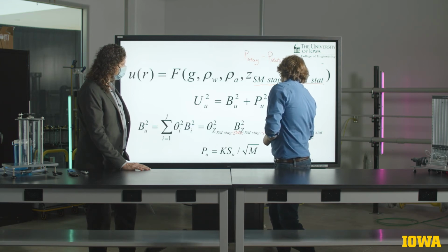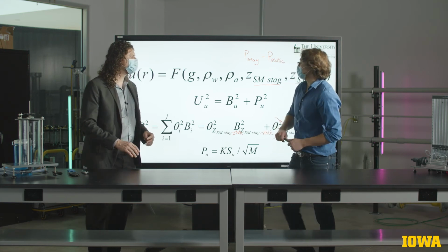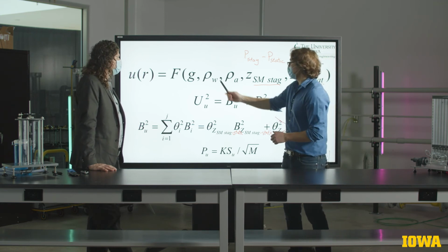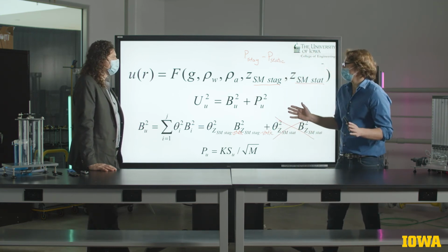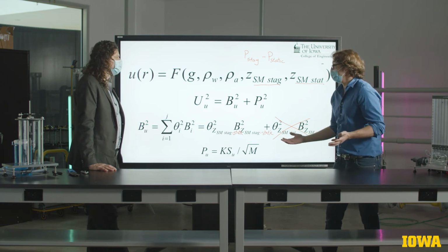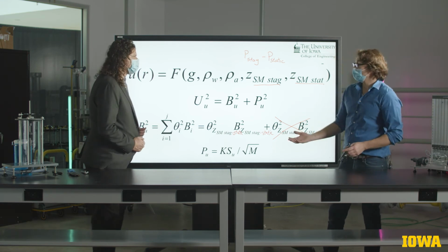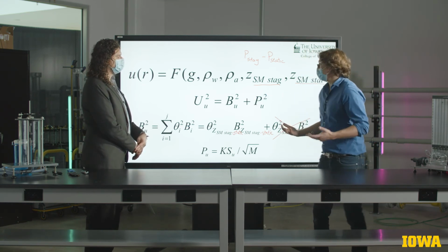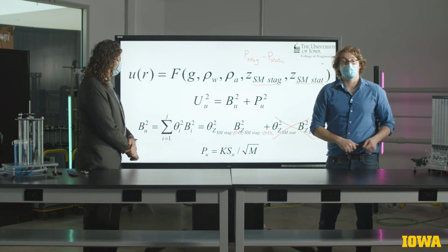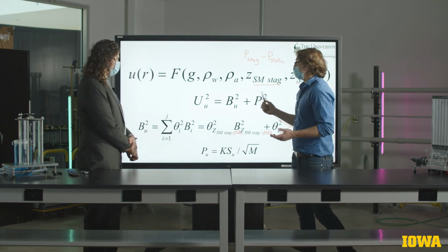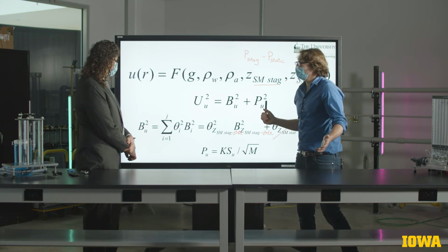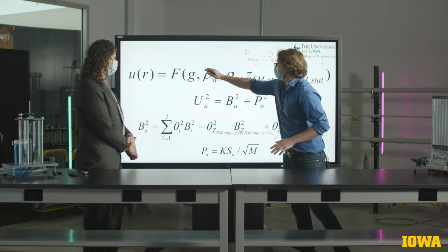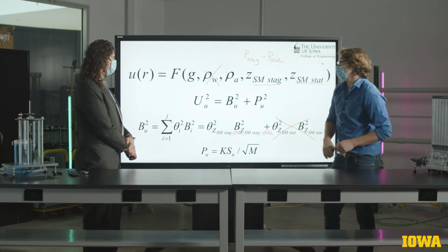The other thing we should be conscious of is that we have two densities here, one of the air flowing through the pipe and the second of water. Now the reason that water is included in there is because of the use of manometers, right? Water is acting as our gauge fluid, and uncertainty in the density of the gauge fluid will mean that you're less precise in how you convert the manometer head into a pressure. Our readout is digital, right? We're using digital pressure transducers. So we don't need to worry about this, and we can eliminate this from our uncertainty considerations entirely.